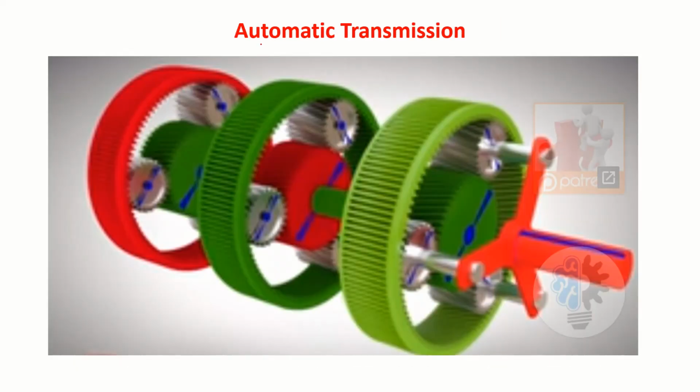Now let us continue the concept of epicyclic gear train for developing a multi-speed automatic transmission system. Look here, I have sun gear, planet gear, ring gear. This is one gear train. There is another gear train like that. Another gear train. Three gear trains.